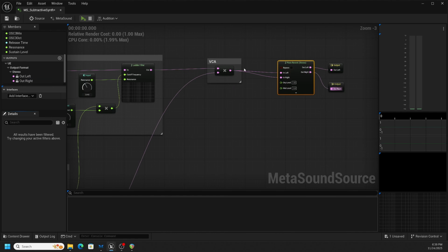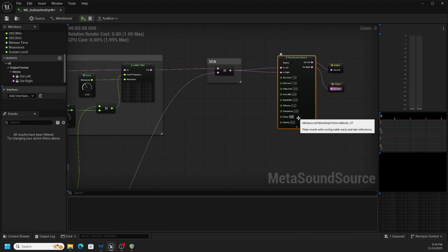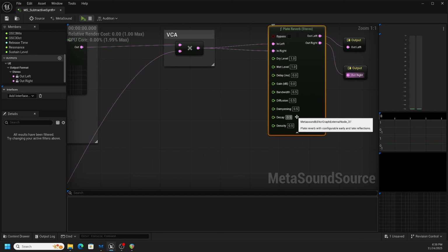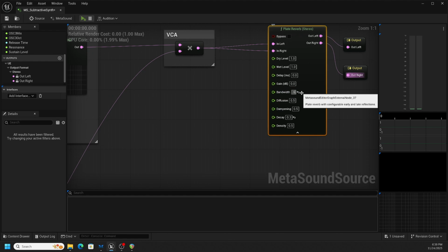So we're going to wire both of the mono inputs for our voice to both inputs here. Different reverb units or effects work a little differently in this regard, but in our case, wiring both of them seems to give the best result. I'm going to increase our decay time by decreasing this value here, and I'm going to go with something like that. I'm going to make it a little bit brighter than the original default. The nice thing about this reverb is it does have an EQ already built in, so you're not fighting that really metallic sound we can get when too much high end is going into and out of the reverb.